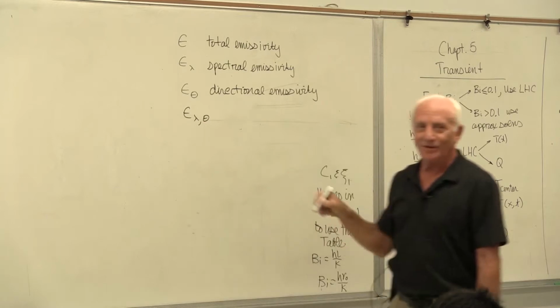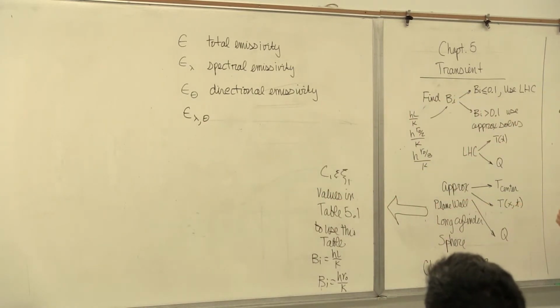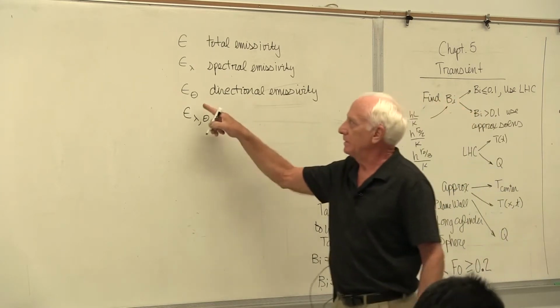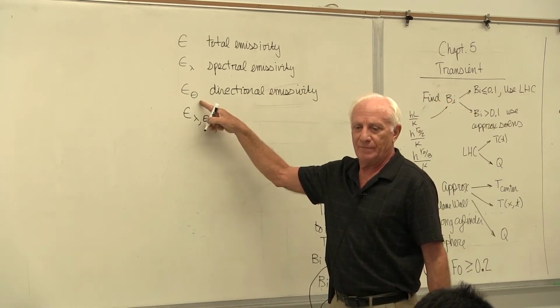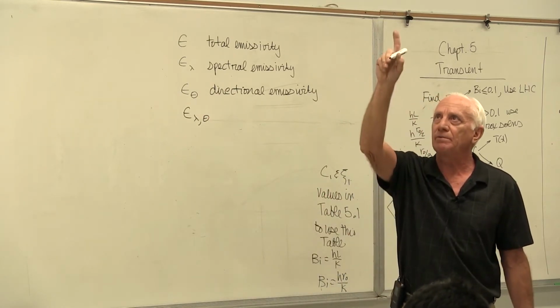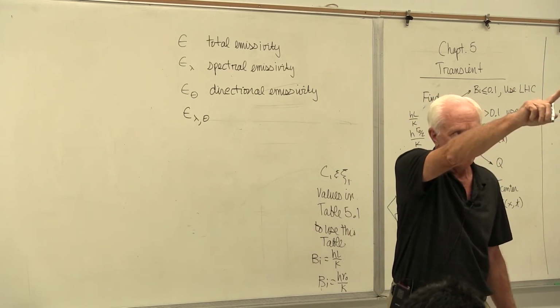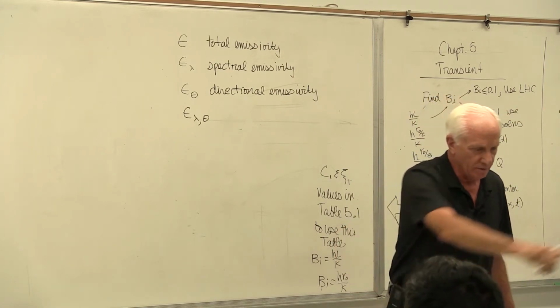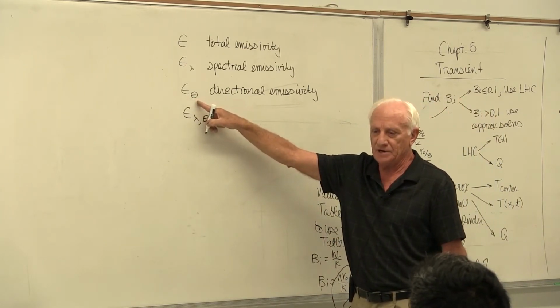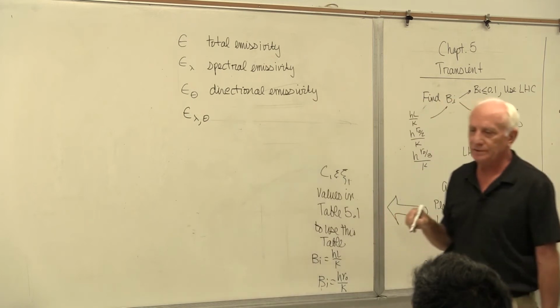That guy is called spectral directional emissivity. Oh yeah, chapter 12 is big on definitions. Big on definitions. The language of radiation. What this means is that the emissivity might depend on the direction that it's emitting radiation. Is it emitting radiation normal to the surface, vertically up, at 45 degrees from vertical, at 70 degrees from the vertical? If epsilon depends on the angle theta, measured from the vertical, that's called directional emissivity.